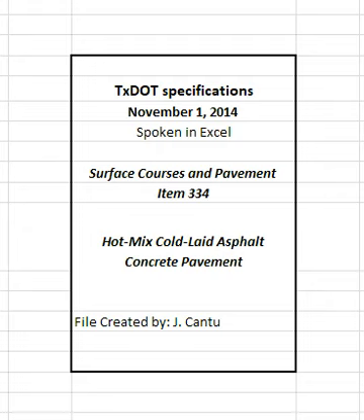4.2.3 Storage of the asphalt mixture. Store the asphalt mixture in a surge storage system or in a stockpile. Provide a smooth and well-drained area, cleared of trash, weeds, and grass if the asphalt mixture is stored in a stockpile. Build stockpiles in a manner that will minimize aggregate degradation and segregation. Avoid contamination and mixing of stockpiles.